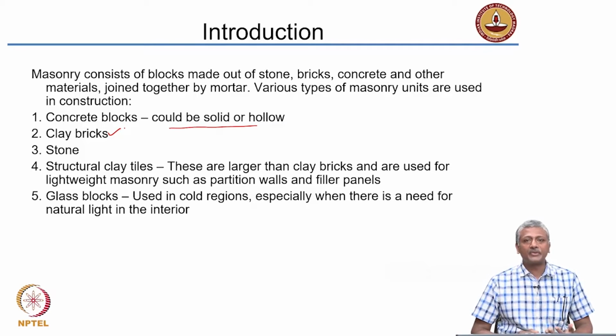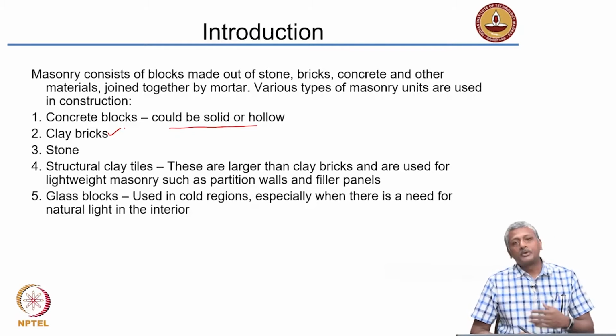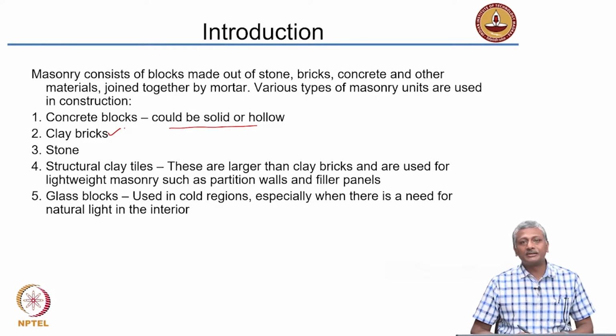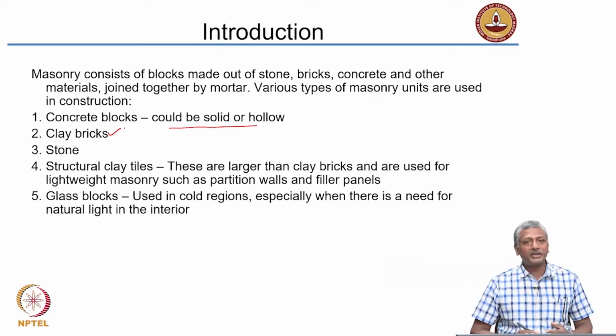Stone, of course, has been part and parcel of our heritage monuments. Even today, some of the modern structures that are coming up, which are not made with concrete or reinforced concrete, are being made with stone. There's a lot of stone structures still being constructed. The difficulty again is obviously getting good quality stone, because for stone structures you would need stones which are of fairly large size without any defects, and sometimes that becomes very difficult because these are naturally mined, and in many cases there may not be enough good quality stone available.